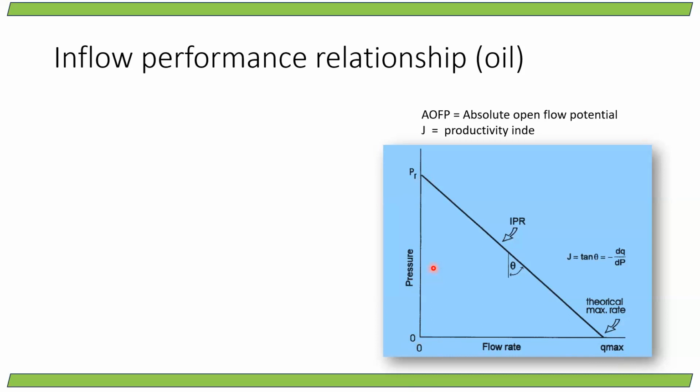That means if the wellbore pressure is equal to the maximum pressure, which is equivalent to reservoir pressure, the production of your well will be zero. So here there are two cases. Wellbore pressure, on the y-axis, has two extremes: one is reaching zero, another is reaching the maximum. Once wellbore pressure comes close to zero, the production will be maximum. When the wellbore pressure comes close to the maximum pressure, which is equivalent to reservoir pressure, then there won't be any production.